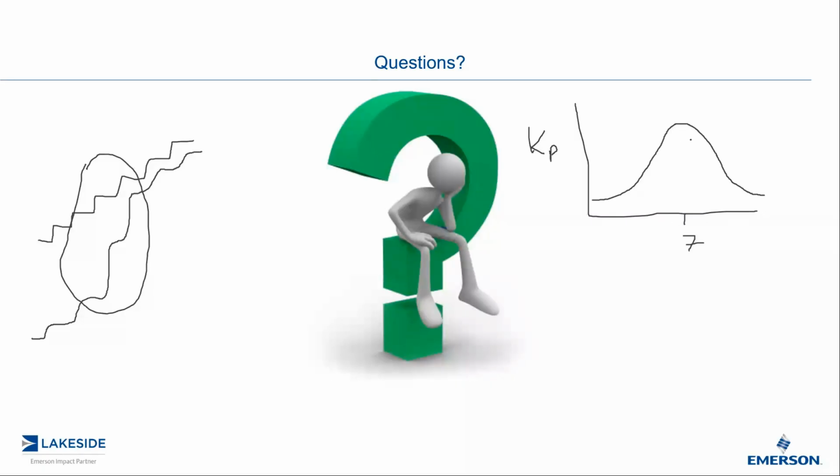So we need to understand how our process is changing over the operating range, and we need to understand that before we can even implement an actual adaptive gain. And so what I would do then is, knowing where we are operating on our pH, I will adjust the gain based on where we are.